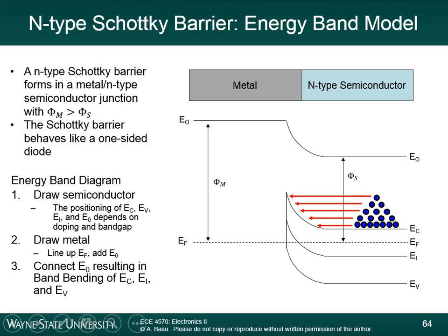This is very similar to a diode. It forms an energy barrier. And this energy barrier has a height, and the height of this energy barrier is the built-in potential of the Schottky barrier diode, just like the PN junction. Okay, so there's a lot of similar concepts here. This distance here in the band diagram is Q times V0. So let's say, for example, this distance here was like 0.6 electron volts.